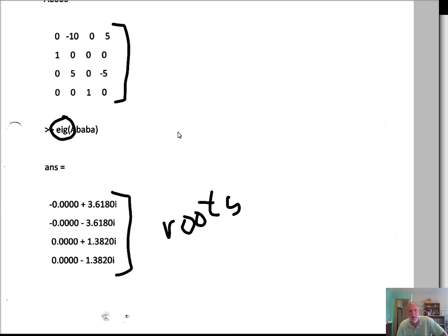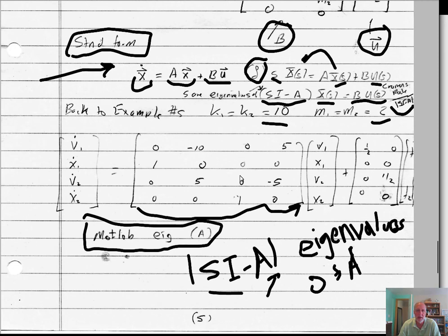Again, the nice thing about this, notice that now we can use a MATLAB function to find the roots rather than having to find that polynomial. It automatically finds it for us. So we can get the roots. So any problem, let's say we had 100 masses, that's a lot, all connected together with springs. We wouldn't have to Laplace all 100 equations. We would simply redefine the velocities. So we'd end up with 100 positions and 100 velocities. So we'd end up with 200 equations.